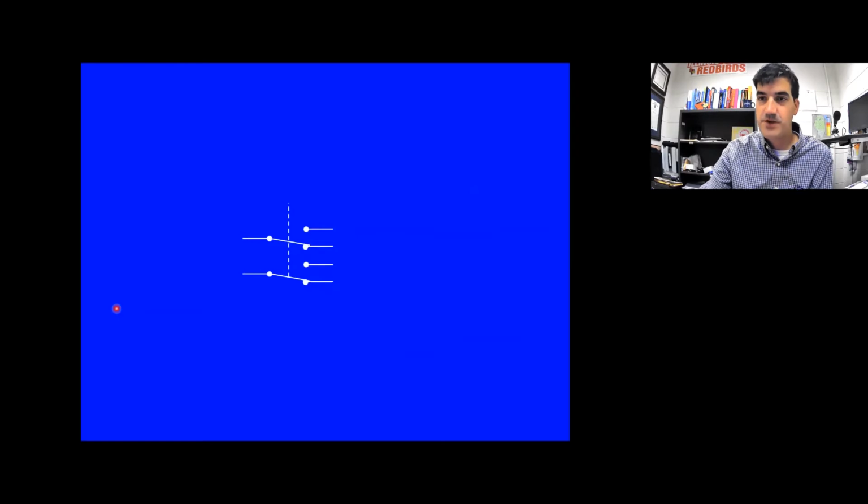All right, so we can build this up. We're going to build up a relay. We've got a switch. What kind of switch is this? Well, how many inputs do we have? We have two, 1, 2. So it's a double pole. And then how many outputs do we have per input? We have 2 possible outputs per input. So it's double throw. So putting them together, it's a double pole, double throw switch.